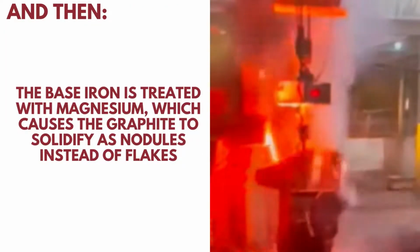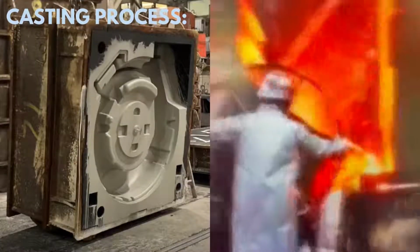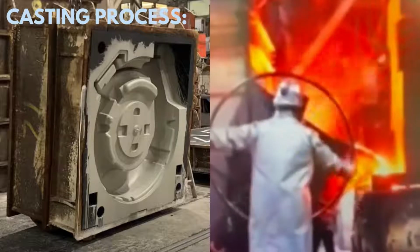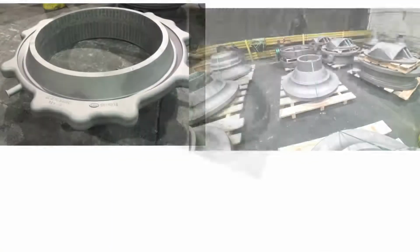The base iron is then poured into a ladle containing magnesium. The reaction with magnesium is what causes graphite to solidify in spheroids instead of rosettes or flakes. The reaction is highly energetic. Once treated, the iron, which is now ductile iron, is poured into sand molds made from highly engineered patterns based on customer models or drawings.